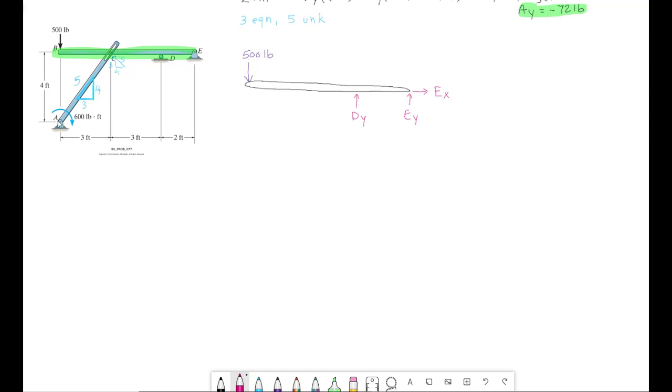Okay. All right, so the force at C, right? When we drew the free body diagram of AC, that normal force was pushing up and holding it from rotating down through. But now we're looking at the force on BC. So the force on BC is going to be equal and opposite to the force that was on AC. It's going to represent this moment and how it's translating into BCD as pushing down on that object.